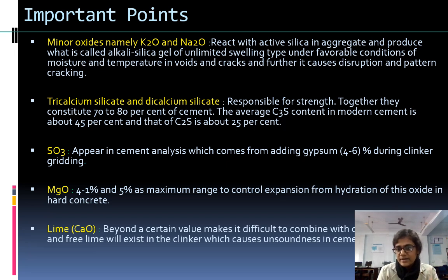If this gel is present in our concrete and moisture or temperature conditions are favorable, it will keep swelling. This swelling leads to expansion, which leads to voids and cracks, and is one of the reasons you can observe cracking in concrete.